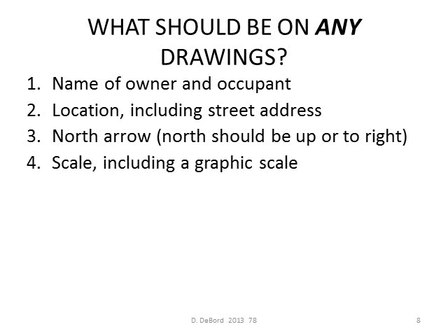The scale has been set in the codes to be a minimum of 1/8 inch per foot, and then we would sometimes blow up plans to 1/4 inch or more for certain rooms to show more detail. And sometimes you would have key plans or other overall plans that might be 1/16 of an inch or something, but you had to have everything shown at 1/8 inch minimum so that people could actually see it.